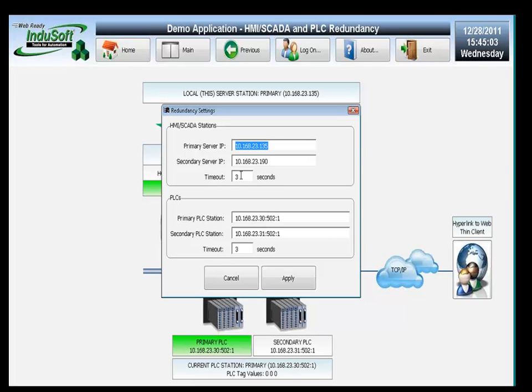So there is a trade-off there, but I can say that in typical applications where you have a local network, a control network, anything from 1 to 3 seconds seems to be reasonable and seems to be good enough to avoid false switches and also to switch within a couple of seconds so you do not lose important data if the hot station goes.